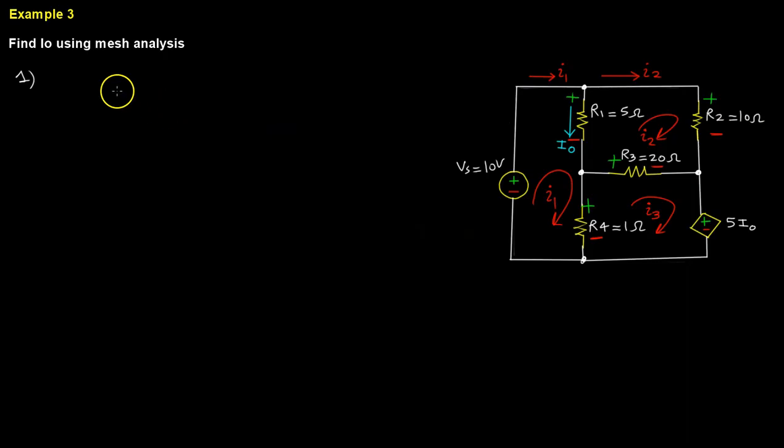So I'm again going to go up and see a negative Vs because I see the minus sign first. I'm going to go up and get to the plus side of R1. The current I'm going to see is I0, so let's declare that first, call it I0 first and then find more variables for it.